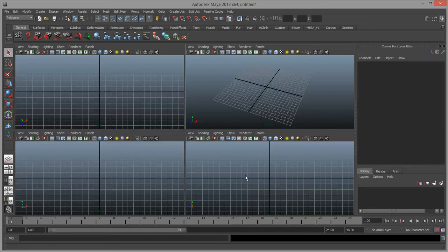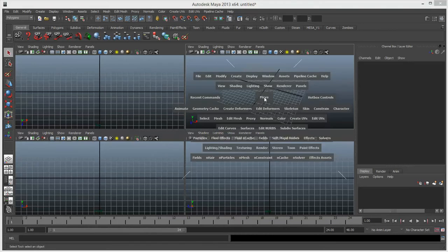Units are customizable in Maya, but just assume that it's any arbitrary measurement for now, that you might need an inch, a foot, whatever you want it to be. But this makes it very easy to line things up and snap them to get them all lined up and neat. Oftentimes we do want to move in and out of these views, and how you do that is by pressing the space bar, but if you hold the space bar you're going to see this huge menu pop up full of different options. So don't hold the space bar. In fact, if you hold the space bar and you move the mouse, wherever your mouse lands, it might select that action.